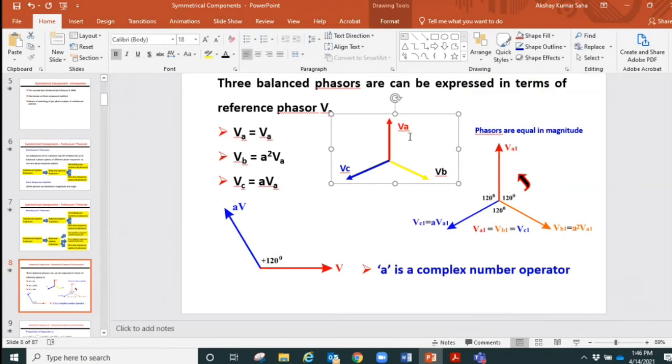We won't be able to stay with this general one, where there was no positive, negative, or zero sequence. Before today, you never heard of positive sequence voltage, negative sequence voltage, or zero sequence voltage. There was only one voltage, VA, VB, VC. But now the voltages will also be like that: positive, negative, and zero sequence. It also applies to the current.